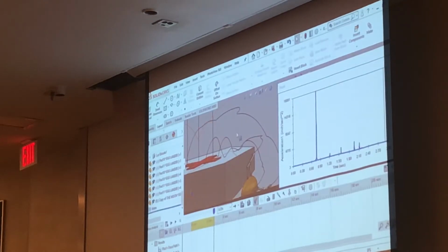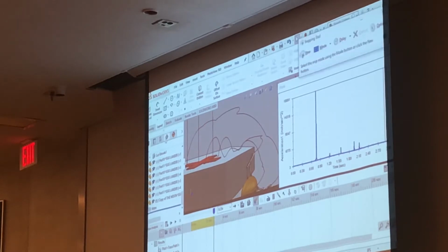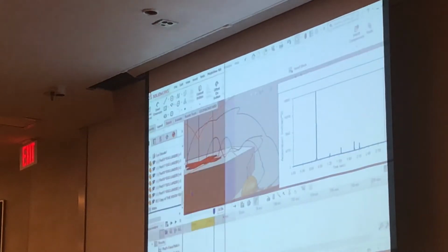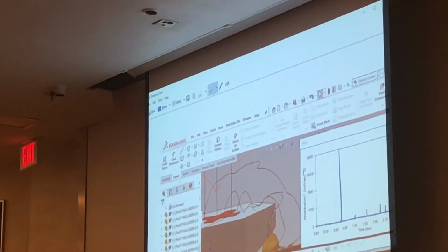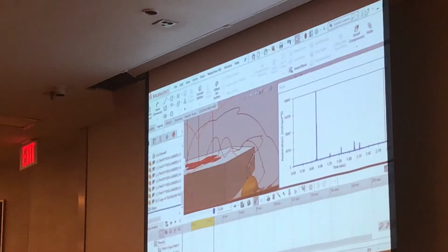So what you're going to want to do is have your trace paths, have your graph on the screen, and then you can just use the snipping tool to take a big capture of the entire screen, and then you can use this ink pen tool here, and very crudely write in the values you use. So you can do like K equals 1, C equals whatever value you use. So just type or write those values in so we know how you define your suspension, and you would save this as an image file and submit that to D2L.